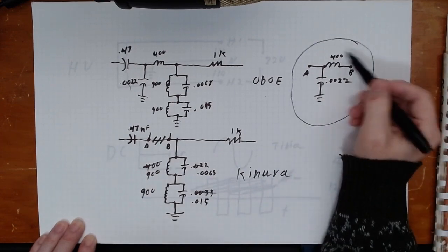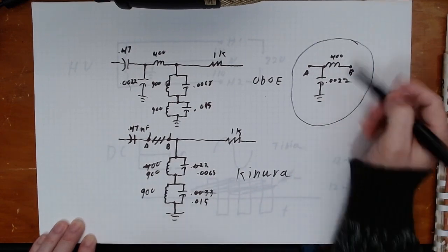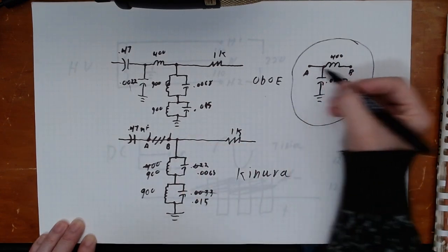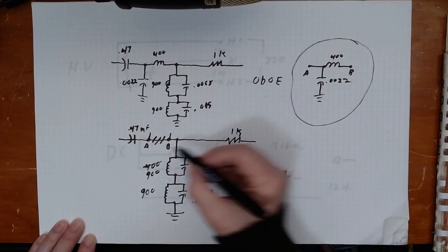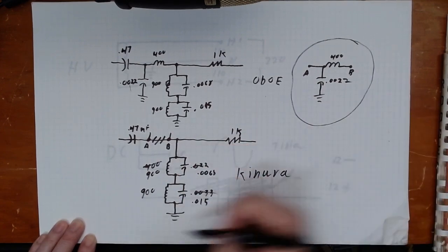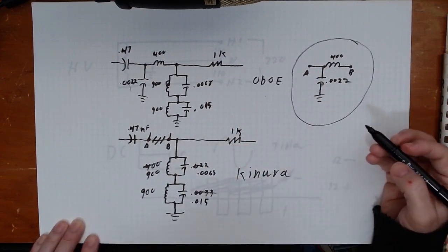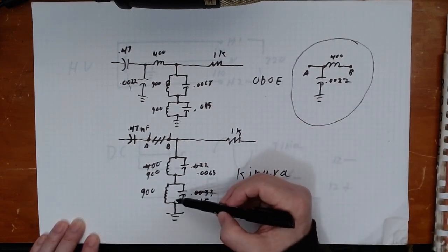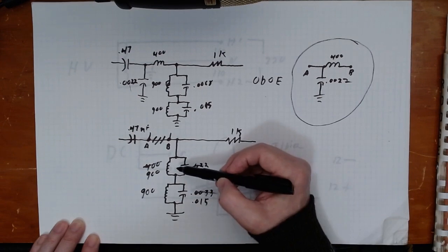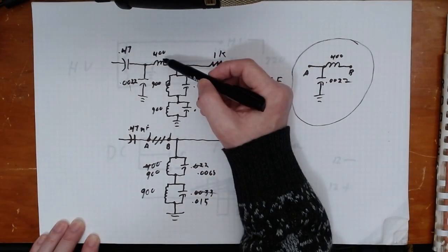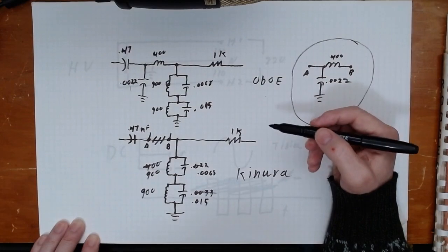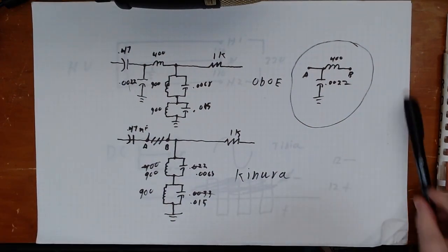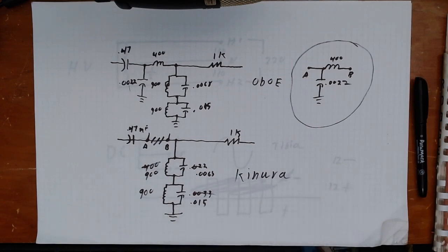So I can put these two components wired up on a separate board, mount that near where this is, create this insert point, run the wires from A to A, B to B, change these values, and we should be home free. So looking at this, I have a 900 turn coil and I have a 400 turn coil. I need a 400 turn coil and two 900 turn coils. So I've got to come up with one 900 turn coil to make this work.